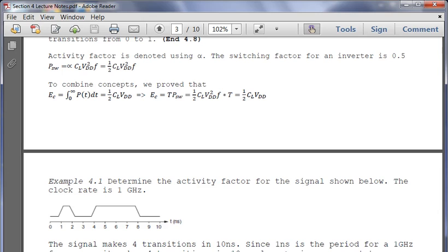So, for example, if you recall from my advanced digital systems course in computer architecture, where we were talking about drawing a circuit that does R-type and load word only, we took out certain portions of the circuit. We took out branch, we took out jump. We only had certain paths. The benefit of being able to do that, other than just understanding the circuit, is that we can use power gating techniques and activity factors to say, if I'm just doing an R-type instruction, I only provide a minimum amount of power to the data memory to be able to save the data. Does that make sense?